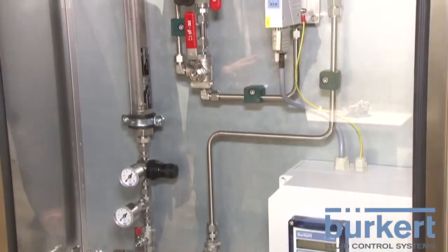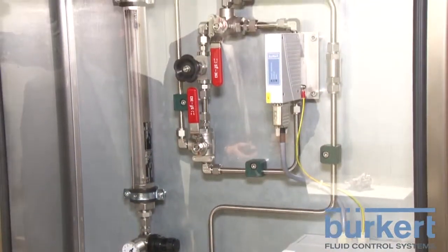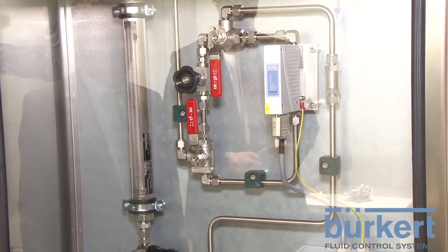Especially if you have a water source like groundwater coming out of the ground, you have the problem that you have iron or manganese in the water. Maybe you know it from at home: if you open the tap, you get red colored water out of it, and the reason is iron or manganese. There are also regulations that the level of iron may not be higher than 0.5 milligrams per liter, and manganese 0.05.